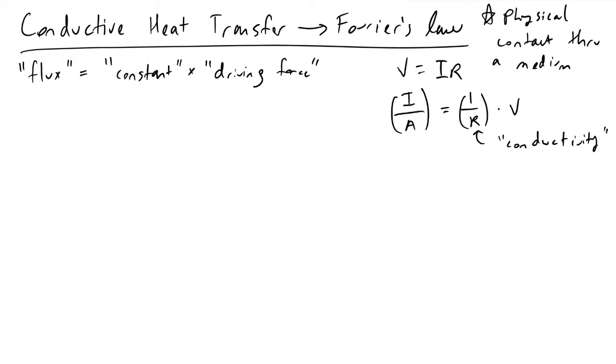And so getting into it now, if you look up the Wikipedia definition of Fourier's law, what you're going to find is this. It's going to tell you that Q with a bar on top, telling us that we're looking at a vector, a flux vector of heat, is equivalent to minus little k times the gradient of your temperature. And this looks a little bit scary, but don't worry about it. So little k is nothing more than the thermal conductance or conductivity of your material.